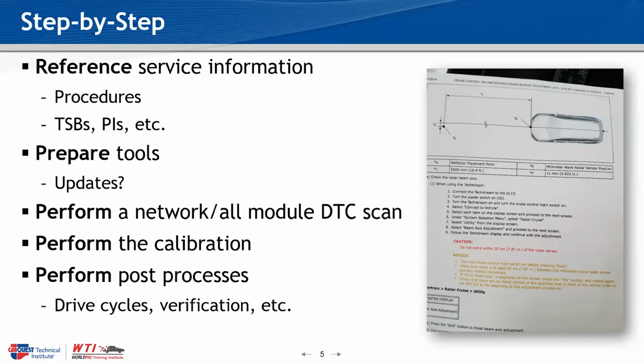Now, GM did come out with a lift kit and a software calibration for Silverados about a year ago. It was a 2-inch lift kit, and it recalibrated the sensors to work with that lift kit. But 2 inches is relatively mild. You start getting into 4, 6, 8-inch lifts, and that's a whole other program. But even at a 2-inch lift, they recognize the need for a calibration to adapt all of the systems. Absolutely. So that's important.